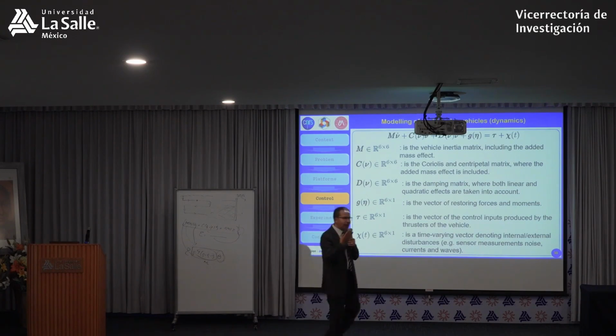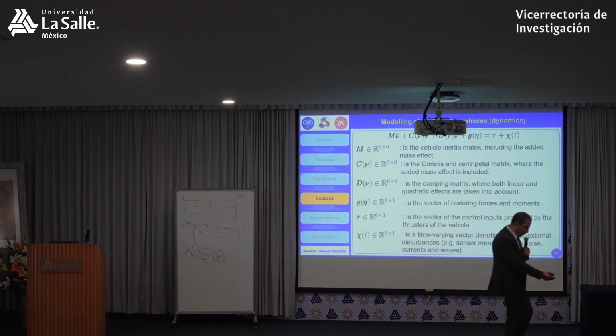What is the added mass effect? Look, I'm walking here, I move my legs in a very easy way. If you ask me to go inside the pool and try to move, it will be more difficult. Why? Because there is a liquid, there is water surrounding me. So when I try to move my leg, I feel that my leg is heavier. And this justifies this term that we call added mass. It's like the volume of water that you remove when you put your leg inside the water.